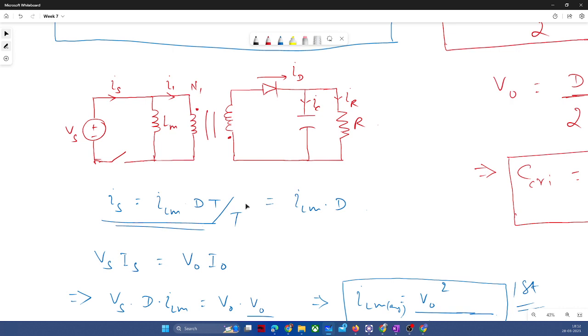What is your specific doubt in the problem, that we should not use this magnetizing inductance? No, sir. Actually, transformers only have magnetizing inductance, whereas in a flyback converter this is not a transformer. They say it is a coupled inductor because it stores energy. Since it stores energy, it can be called a coupled inductor. Do you have any reference for that, or have you analyzed it yourself? In other PMRF sessions, sir told us that this is a coupled inductor which stores energy.